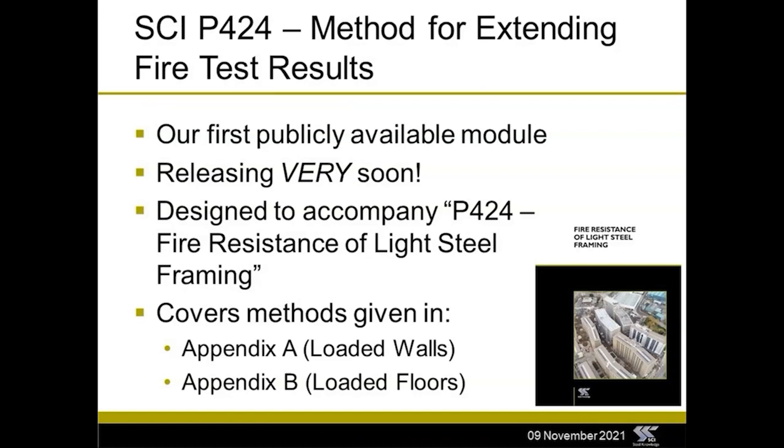And essentially what these methods are aiming to do is to take a set of test results from a physical fire test on a particular build-up and modify those test results or apply those test results to a design scenario where your light gauge loaded wall or floor might differ in certain key aspects from your fire test. So you're not looking to have to test every single configuration you might have.